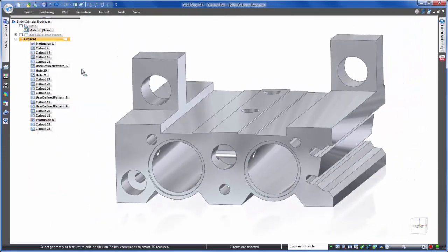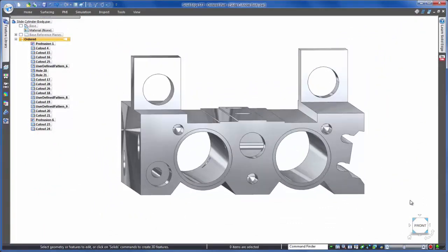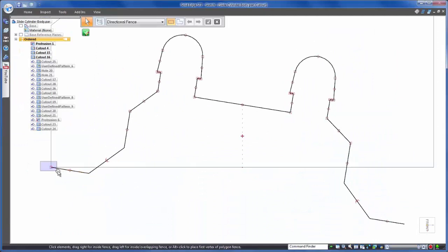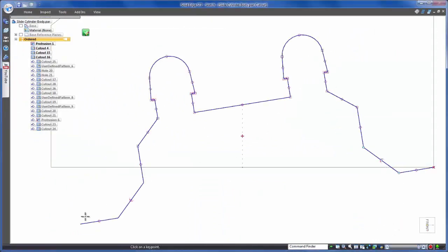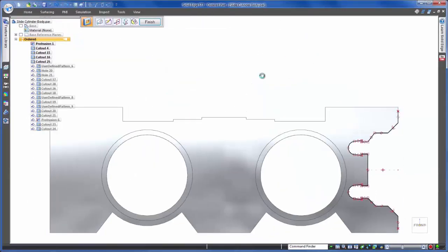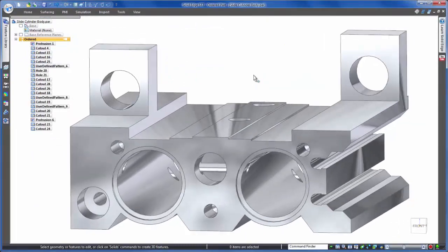Solid Edge's dimensioning tools allow us to input formulas directly. Not necessary here, but we've all pulled out the calculator before. Due to inappropriate design intent, notice that our cut has been shifted. We'll need to go in and fix this. This can easily be accomplished by deleting out the incorrect sketch relationships and then adding new ones.